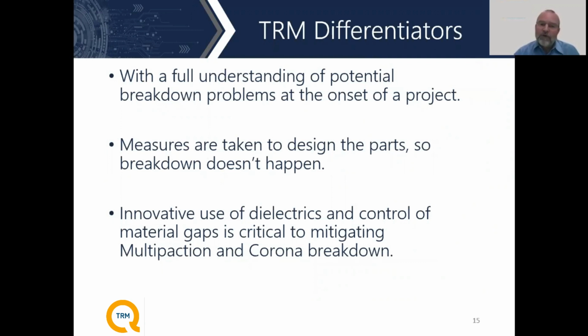Sure. So, what we do when we design parts here is we take a very holistic view of the system, and we go through. The first thing we do is we look at potential breakdown issues, both for multipaction and corona critical pressure. And we actually go in there and we design these parts so that they can't happen.